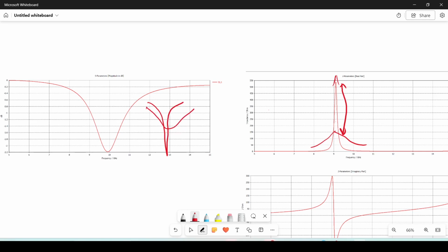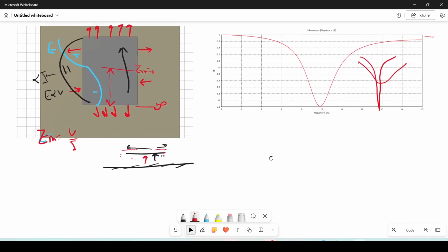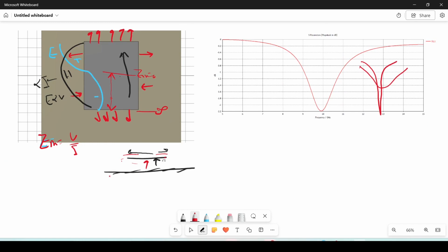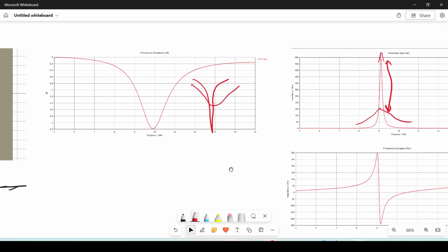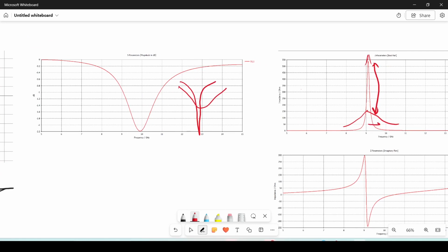Okay, so I can show it more, but the only difference is that in cavities, when you introduce a via or something, it changes a little bit. The existence of the via itself changes the size of the cavity or something. So we are expecting that you will see a little bit of shift in the peak. It's not big, I guess, but as we will see in the simulations anyway, the major thing that will happen is this peak, and a minor change in the center frequency. This is one thing.